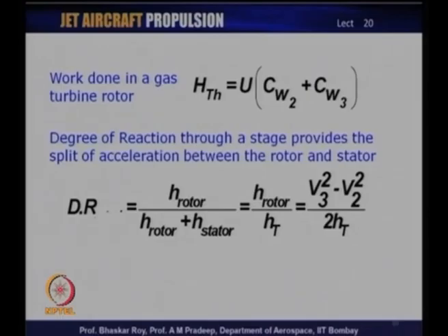Now, let us take a look at the other important parameter that we have looked at, the degree of reaction, which is often used to essentially split the acceleration between the rotor and the stator. We have just seen that we like to have acceleration split between the rotor and the stator, and this is often quantified through this degree of reaction.